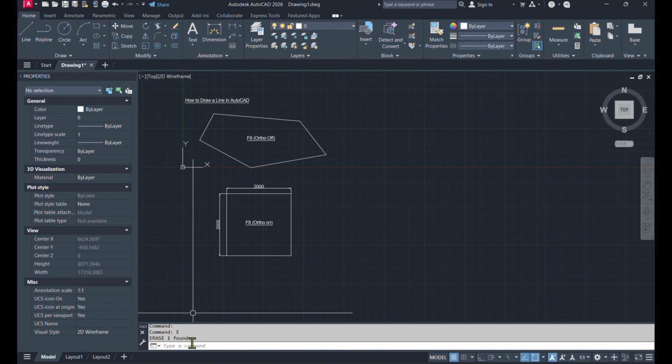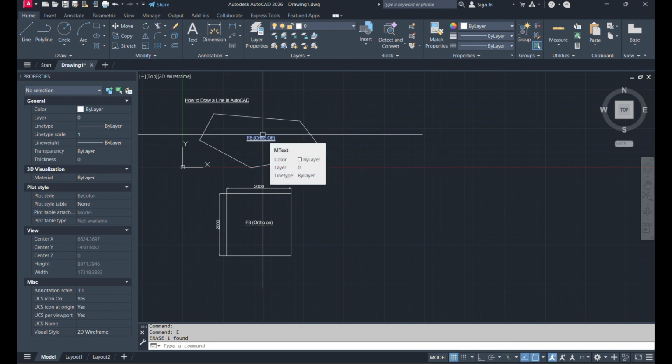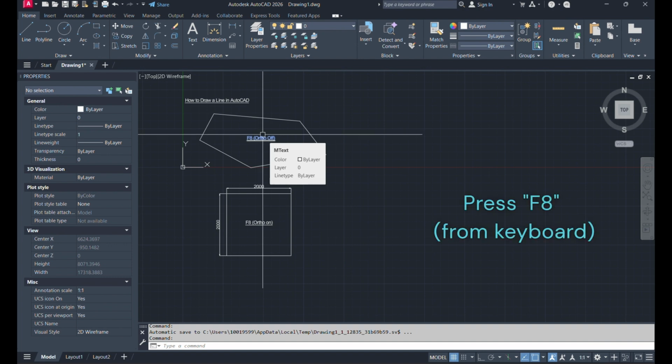To draw some lines, first make sure auto is off to create this compound, because this compound is a non-straight compound. So if you want to try the first one, you can turn it off by pressing F8 on your keyboard.